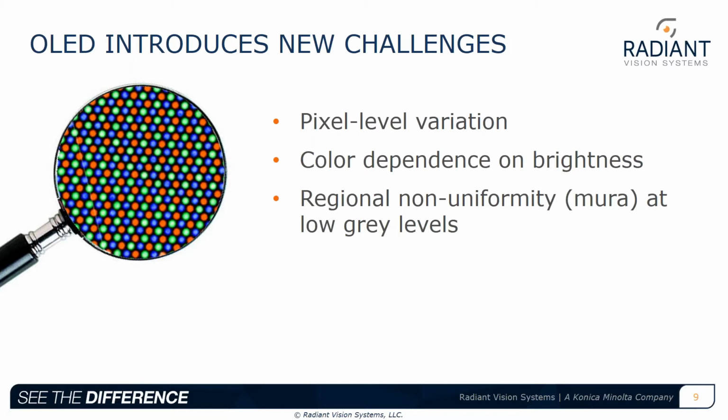Each pixel of OLED is an independent emitter as shown on the left. What we mean by a pixel is any of the red, green, or blue pixels in the image. OLED displays require us to evaluate each pixel for failures. During the manufacturing process, things can go wrong. Bad pixels, dead pixels, and non-uniform pixels can exist, which are hardly detectable by a human inspection process.